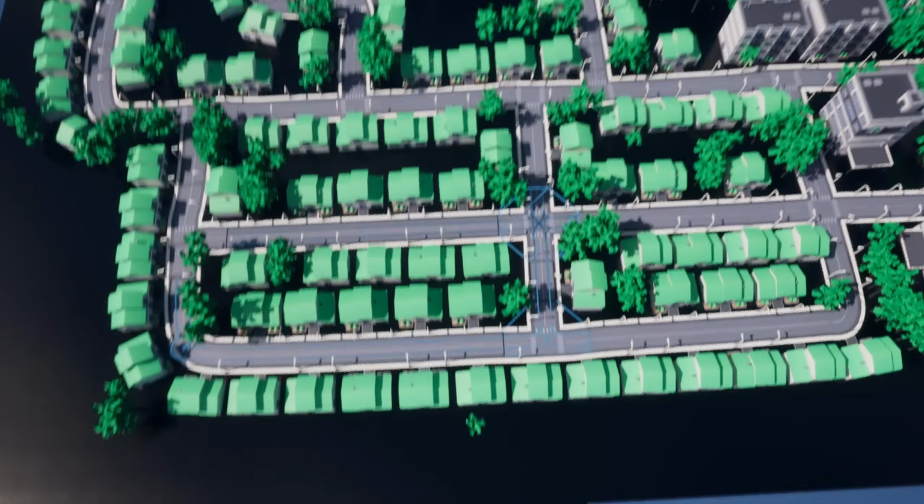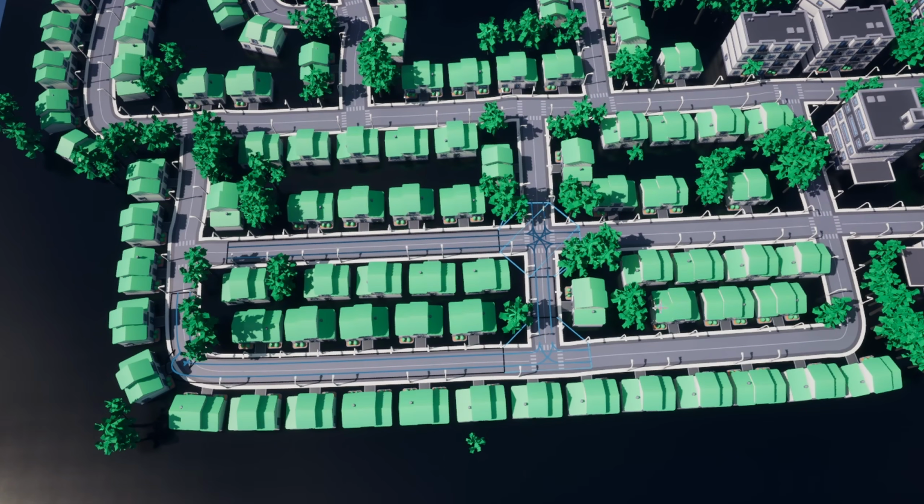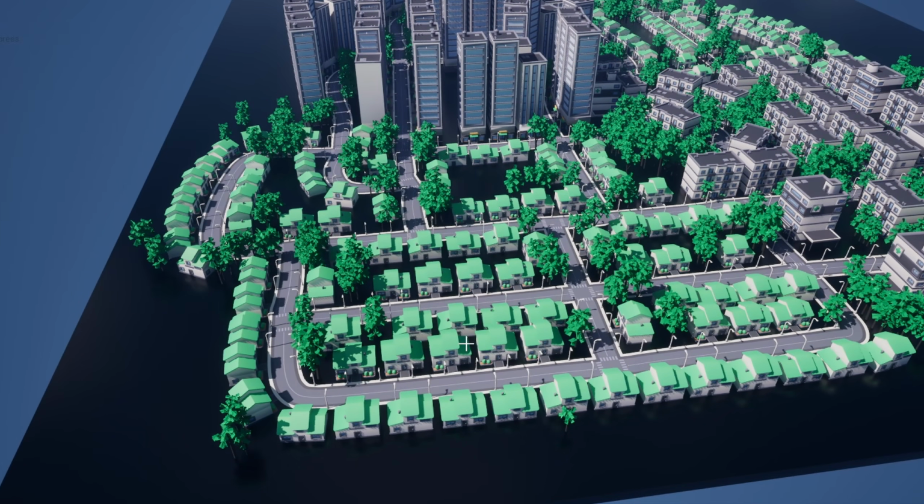As you recall from a previous part when we did the driveways, we had to adjust the actual bounds to be much smaller than the driveways actually are for the trees and everything to appear next to the driveways, because it would not cut out exactly where the bounds were, it would cut out a little bit extra. So you can play around with these values and see which one works best for you. If we take a look here now, you can see there are now 2 rows of buildings. If you recall, we had only one building here because of the large offset. So now we have far fewer vegetations because we have far more packed buildings.